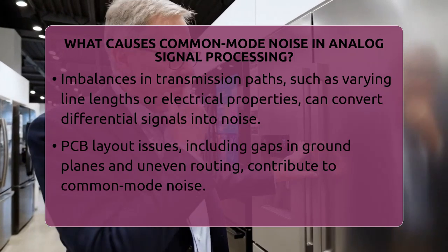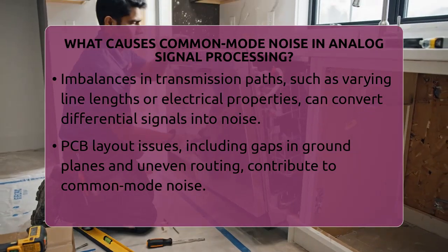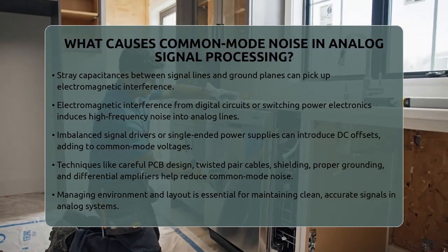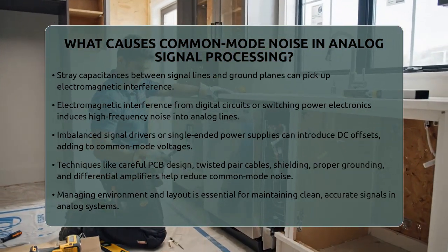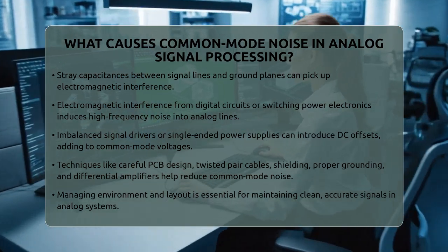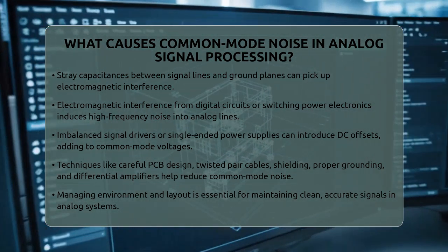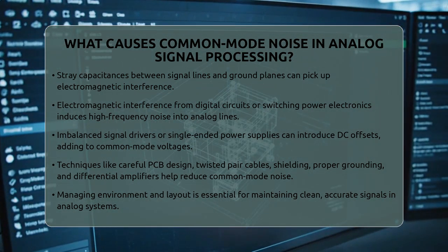Lastly, if the signal drivers are imbalanced or operate from single-ended power supplies, they can introduce DC offsets or imbalances, which show up as common mode voltages. All these factors combine to produce common mode noise that can distort signals, cause errors, or even interfere with electromagnetic compatibility.